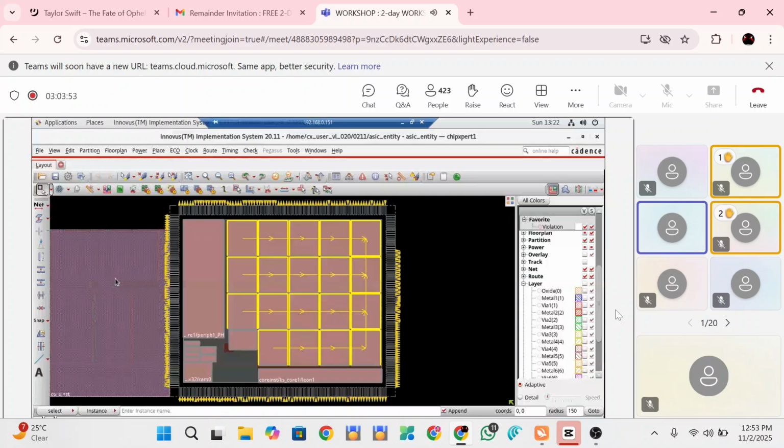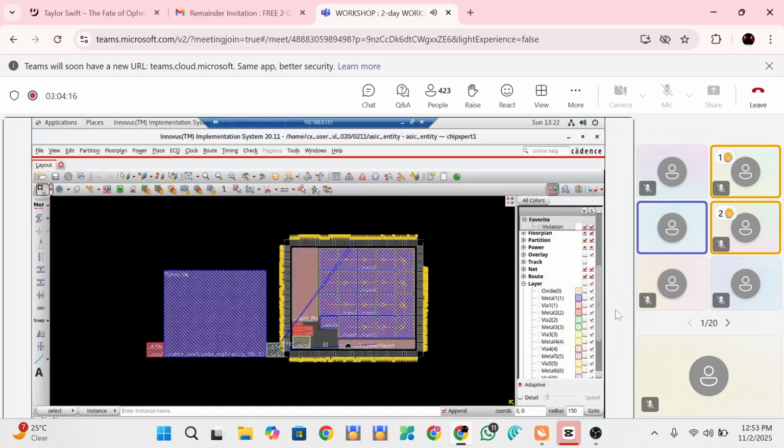It's also for the manufacturing. Once the manufacturing is done, they give small bits of data to check whether all the blocks are working at the required frequency or whether some combinational logic has some issue. Coming to digital verification, there is one more, physical verification, that will be after the design. That is verifying your layout is properly qualifying for all the parameters: shorts, spacing, all considered in verification. That is part of physical design only.